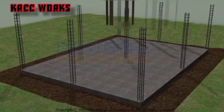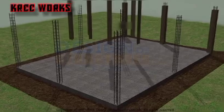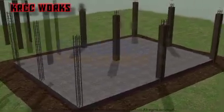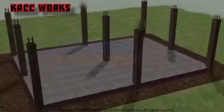Column shuttering. Column shuttering should be rigidly constructed and efficiently propped and braced both horizontally and vertically, so as to retain its shape. The shuttering should be set accurately to the desired line and levels and should have a plain surface.